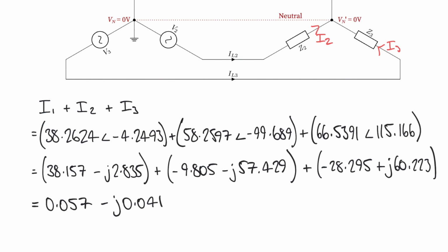So I hope you found this video useful as an introduction to neutral displacement and how we can apply Millman's theorem to calculate the value of our displaced neutral voltage, and how that affects our resulting calculations for voltages and currents in an unbalanced star network.